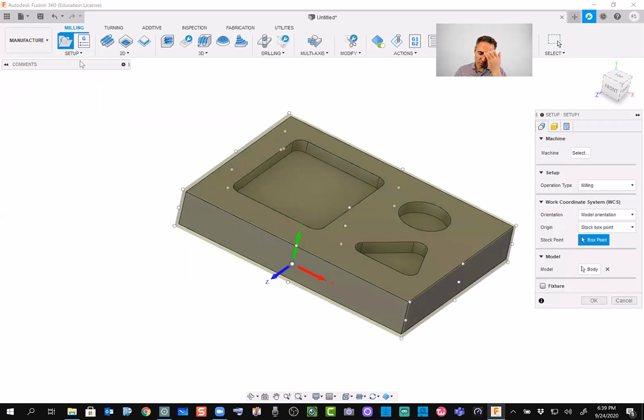Okay, so setup is a very simple thing. Where do I want my coordinates to be? That's the setup. And also, I want to say if this part that I want to do the pocket on, is it something that I need to do pre-process, like before doing the pocket? Like removing and smoothing the surface, or no, the material, the length that I want has been set.